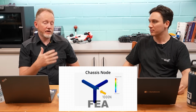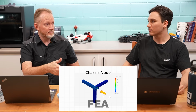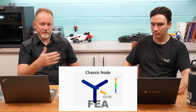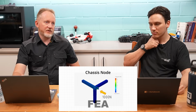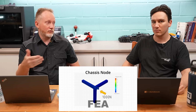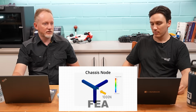It can speed it up, I think, and it's just really another difference between working in an engineering job versus doing this at home. If you're in that engineering field, FEA just speeds things up so much that you just go, no, this is essential. We wouldn't do these structures without it. The danger of these tools when you're starting to use them without having used them quite a bit is it's really quick to get the wrong answer as well. You put the wrong boundary conditions in, or your meshing's not quite right. There's a lot of ways to misread.